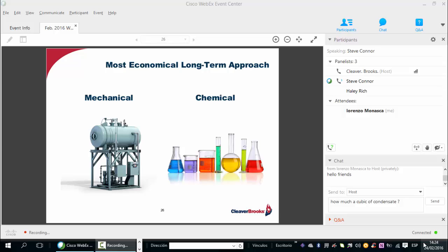Or maybe it's a real solid amine neutralizing or filming amine dosing program, which is injected into the steam supply header so that when condensing occurs, we have an agent present to arrest the problem. Or, maybe it's a combination of both the dealkalizer and amine dosing, working together in tandem. And it's a very important issue which needs to be discussed with a reputable chemical treatment professional.